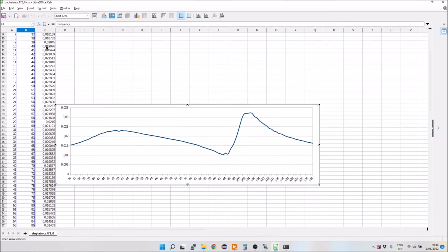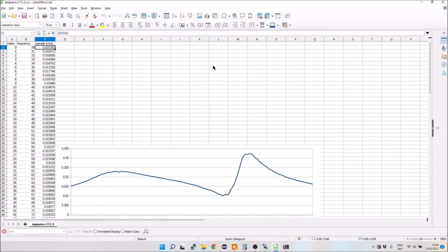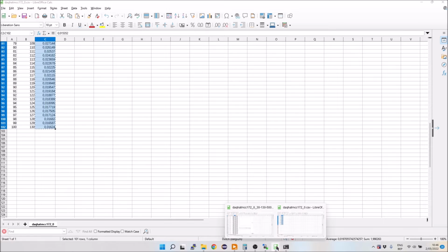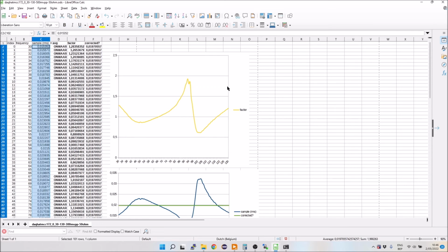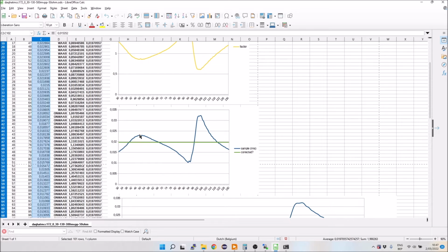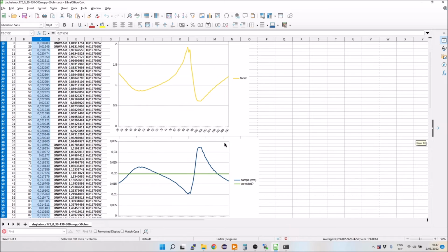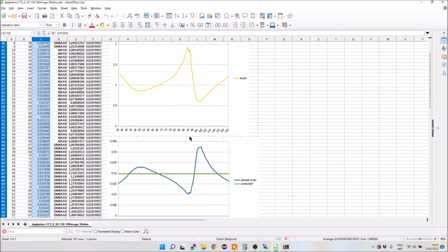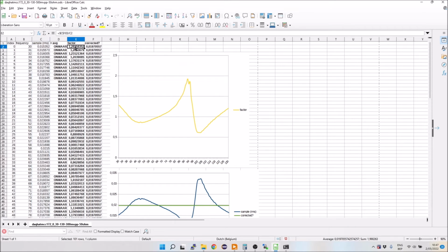So this information that we just captured, I will copy from this spreadsheet, paste it into the correction spreadsheet, and then see what it does. So you see here that these were the original values we sampled a minute ago. This is the correction factor that my spreadsheet calculates to be applied to the input to have linear output, and then this is the predicted linear output. I bet it's not going to happen, but I'm going to try this anyways.